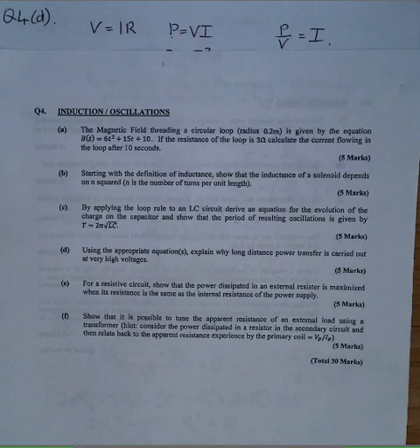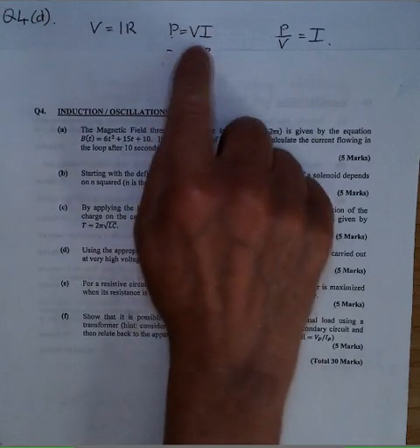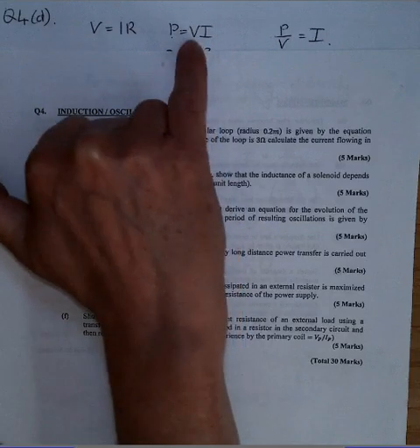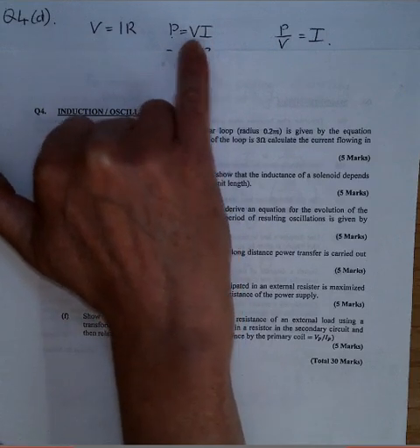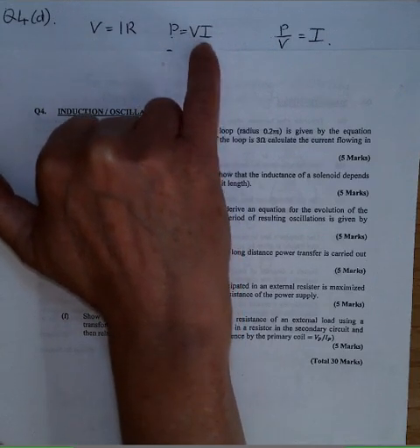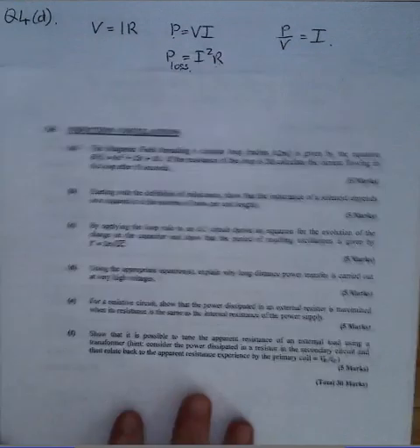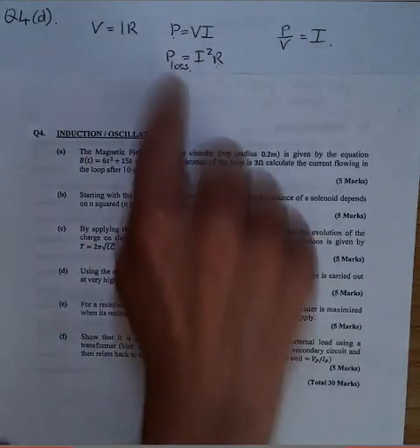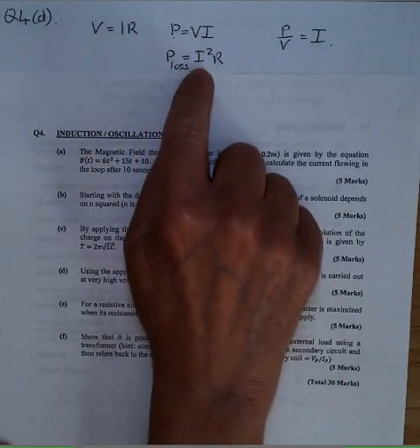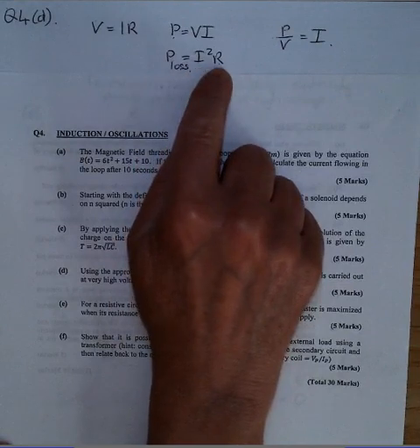And it turns out that if you send electricity at very low voltages, that means you're sending electricity at high currents if you want to supply a high power. Remember, power equals VI, so if we use a very small value for V, then I must be extremely large. And why is that problematic? Because the losses in the cable depend on I squared times the resistance of the cabling.